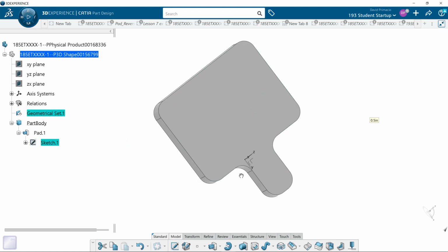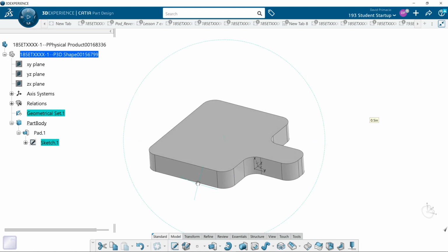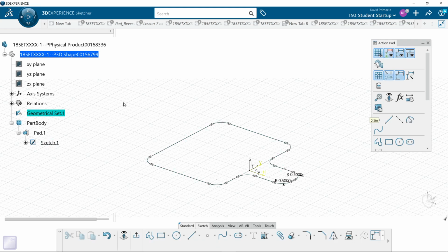See what? Exactly. If I had this part sitting on a tool like this, I've got a 1/2 inch cutter and I'm coming along the side. Am I okay? Seems like it. Okay, so I can machine off this side of the face. Can I make this round with a 1/2 inch cutter? Yep. This face with the 1/2 inch cutter? Mm-hmm. And this face? What was the angle? Half inch. You're not okay. Not clean.